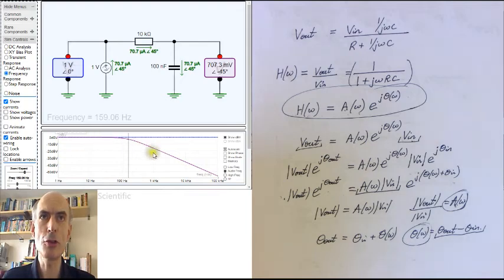This, of course, is just the amplitude response, though. You can show the phase response as well by just clicking the control there, and you'll see the phase response here starts off at 0 degrees, and as the frequency increases, heads down to about minus 90 degrees. You can, by the way, pick up this grey line, which shows where the current frequency is, and move it around if you want to see the performance of the circuit at different frequencies.